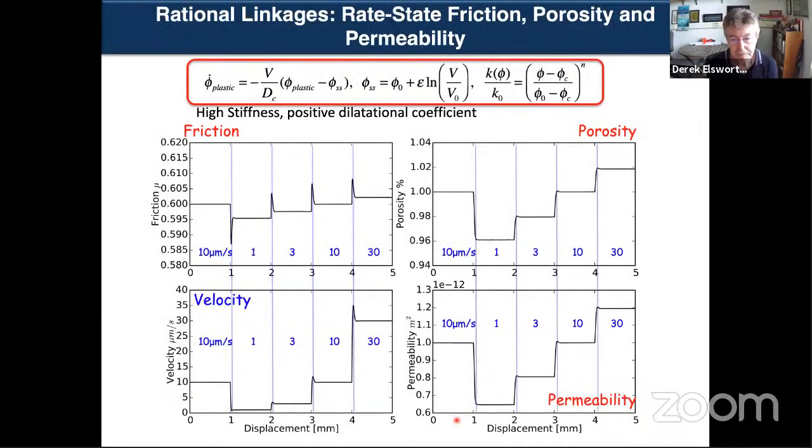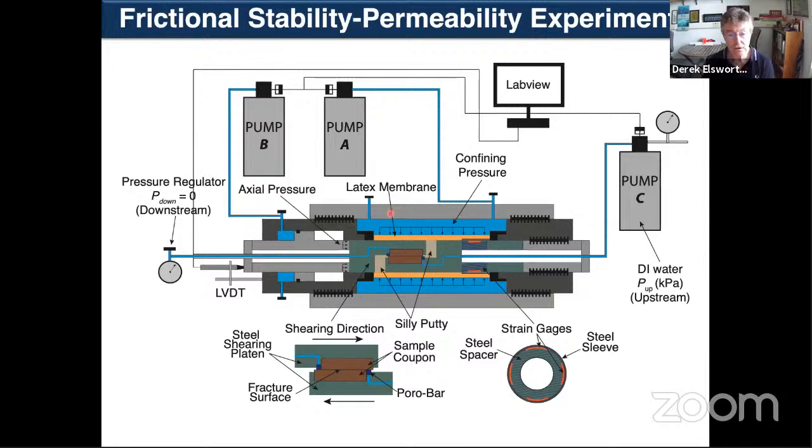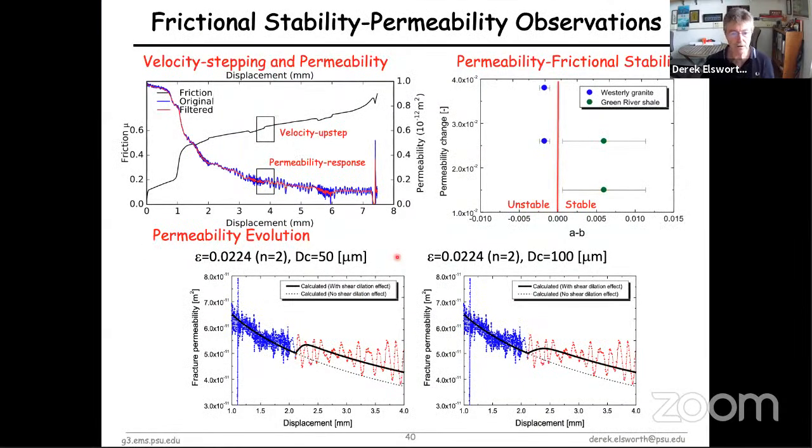We do it in the lab on single sheared samples with fluid pressure and driving flow across them while you shear them. So permeability is measured while you shear them. And typical results would look like this. You measure in the blue dots the magnitudes of fracture permeability as occurs. You provide a reactivation. So you increase the deformation, you potentially increase the permeability. The red dots now are the measurements, and the model of those systems based on rate state friction are the solid black lines you see.